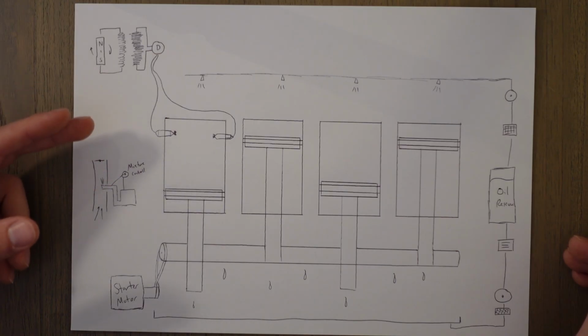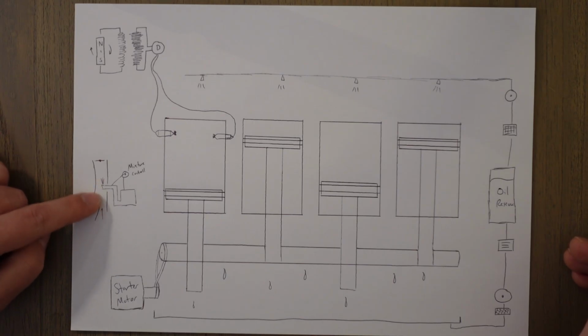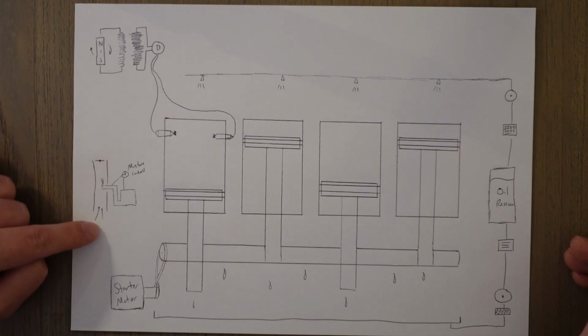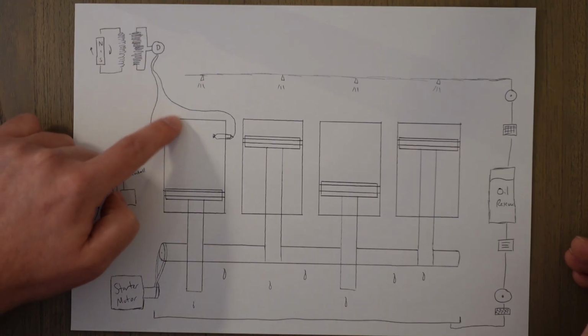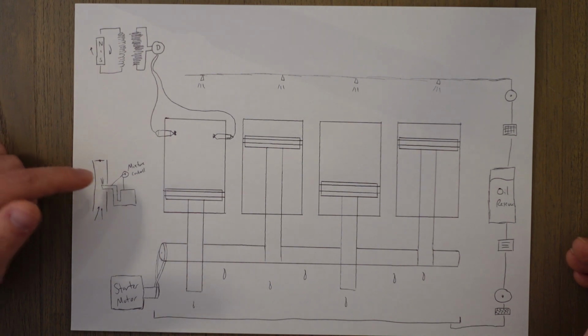The way that we control the fuel mixture is maybe through a carburetor, which is a clever system using Bernoulli's theory to create a low pressure area above the nozzle and draw fuel into the choke and via the throttle towards the intakes of the engine valves, essentially.